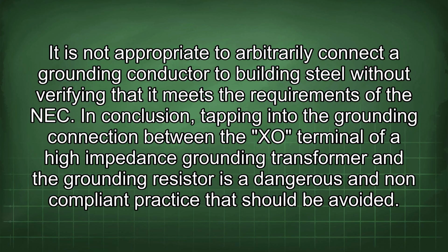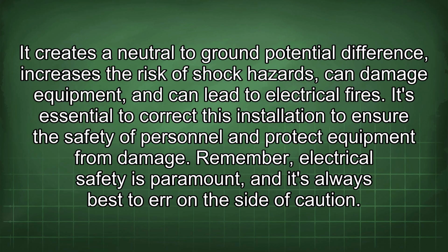In conclusion, tapping into the grounding connection between the XO terminal of a high-impedance grounding transformer and the grounding resistor is a dangerous and non-compliant practice that should be avoided. It creates a neutral to ground potential difference, increases the risk of shock hazards, can damage equipment, and can lead to electrical fires. It's essential to correct this installation to ensure the safety of personnel and protect equipment from damage. Remember, electrical safety is paramount, and it's always best to err on the side of caution.